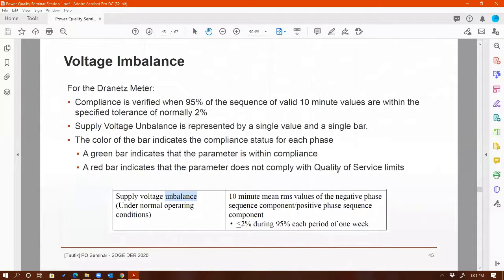So depending on the duration of the time, how much voltage beyond the nominal value should be acceptable by a switching mode power supply or offline power supply. So definitely, percent imbalance would affect that. It's something that you have to consider if you are designing offline power supplies. That's another reason why I think this is important for you.